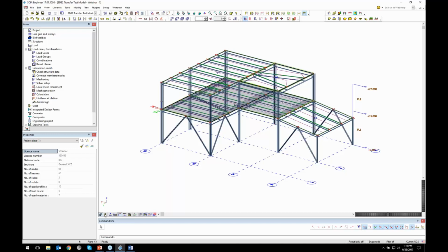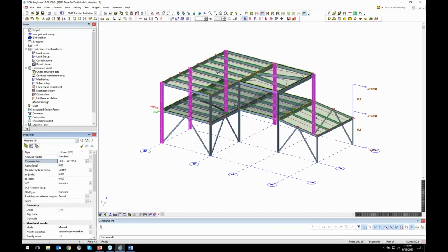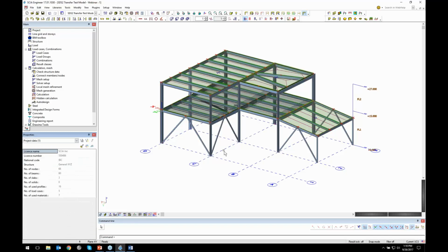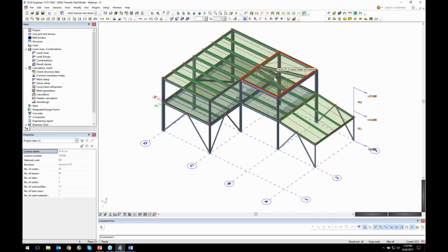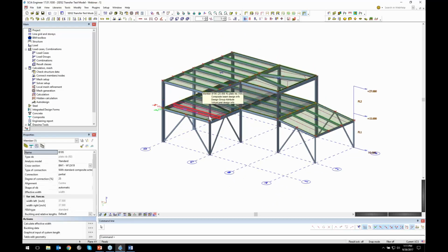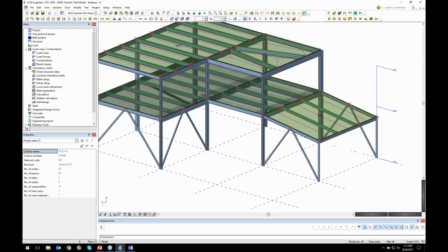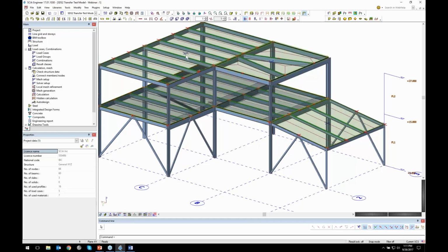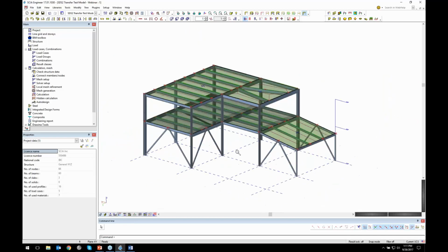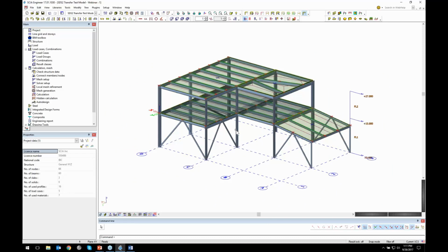In this particular model, you can see we've got a series of different steel columns, and the steel columns are going to be designed for the particular loads in SCIA Engineer. We've got some roof beams, some horizontal skewed beams so that we can see both design and also how those connections would be detailed in SDS2. We do have composite beams on the floor, so we'll look at some composite beam design. We also have some generic roof beams here as well. We have different composite floors and roof decking, some horizontal bracing members, some vertical bracing members. We don't have it in this particular model, but we do also support the exchange of joists. So no joists in this particular example.